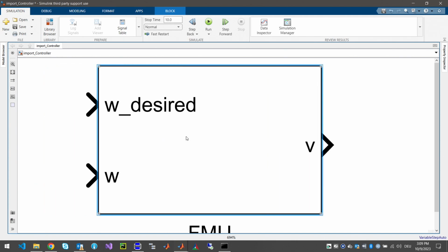So this round trip doesn't really make sense, because if you're working in a pure MathWorks environment, you would probably use S-functions. But I'm just showing that you can go either way. And also this doesn't have to come from Simulink. Obviously you could use a Dymola FMU in Simulink and vice versa.